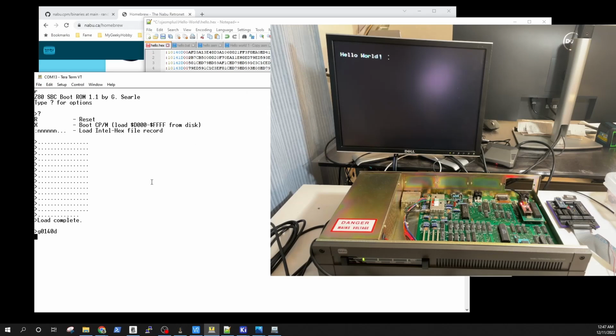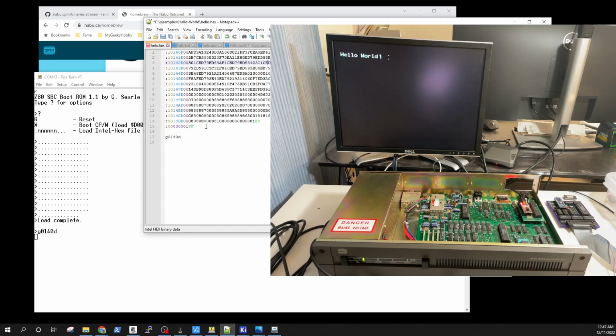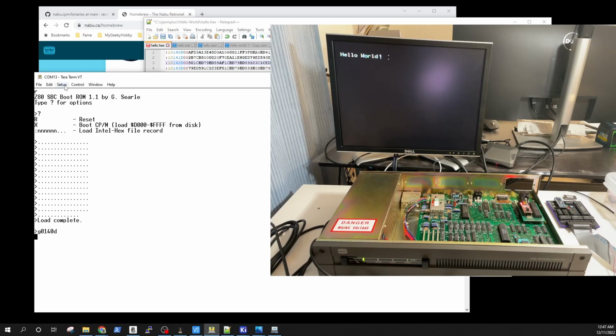We have a very low footprint firmware monitor in the Nabu. We're able to upload hex files into it. In this case, I have to use TeraTerm to introduce that 1 millisecond delay. I'll try to later prepare maybe a Python script that can do this for us automatically, so we don't have to go through TeraTerm, and we can just use Python to add that extra delay in between the characters to automate the whole thing.